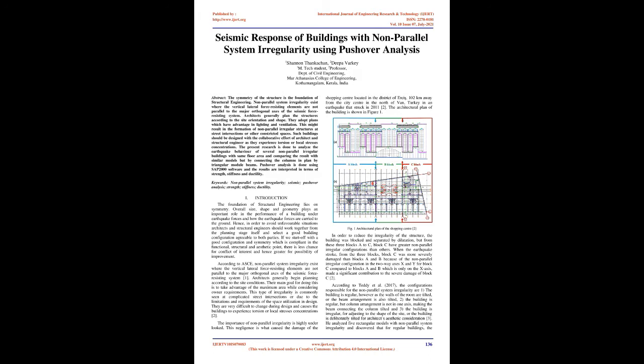If we start off with a good configuration and symmetry which is compliant from the functional, structural, and aesthetic point of view, there is less chance for conflict of interest and hence greater possibility of improvement. According to ASCE, non-parallel system irregularity exists where the vertical lateral force-resisting elements are not parallel to the major orthogonal axes of the seismic force-resisting system.